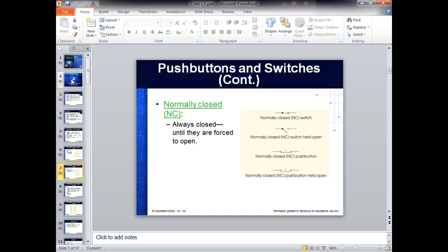We have two versions of the bipolar junction transistor, called an NPN transistor and a PNP. When they designate sinking and sourcing sensors, sometimes they say it's an NPN or PNP sensor. Well, an NPN sensor is a sinking sensor. A PNP is a sourcing sensor. So that's all you need to know. NPN.